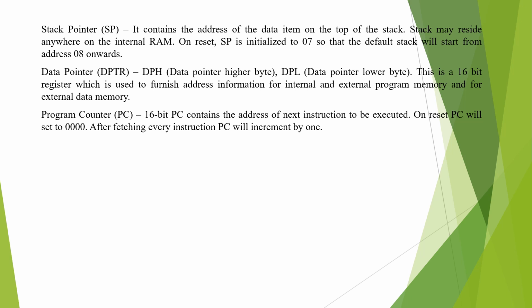The other difference is that in case of 8085 we know the stack pointer address is 16 bit, but in this case the stack pointer address is an 8-bit address, and it can be in any portion of the internal RAM, and manually we can set the address. But the default stack pointer address, that means when we just power on the microcontroller, the default stack pointer content will be 07 hex.